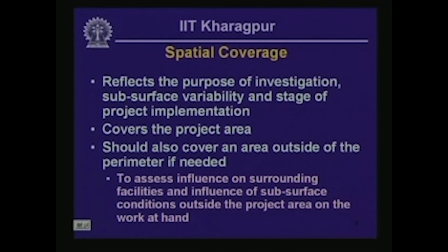If an investigation is being undertaken for a very important project, then the spatial coverage may have to extend a little further out of the footprint of the proposed construction, so that the effect of the proposed construction on the surrounding areas is also properly assessed during the design process.